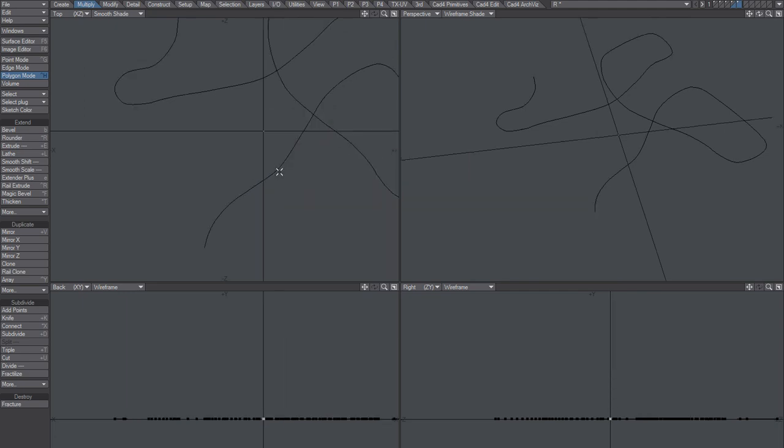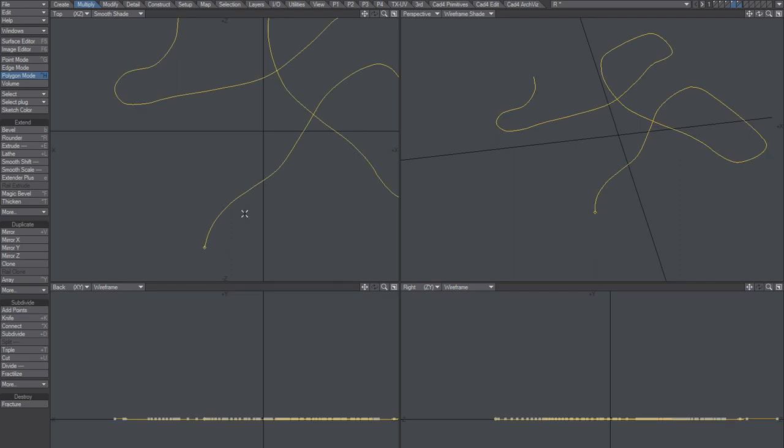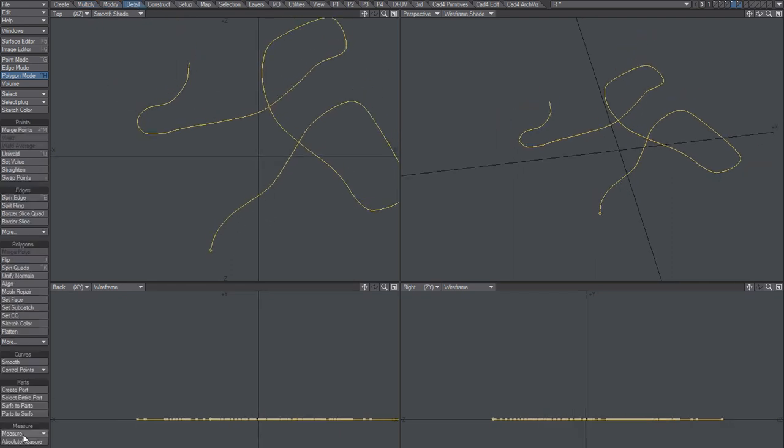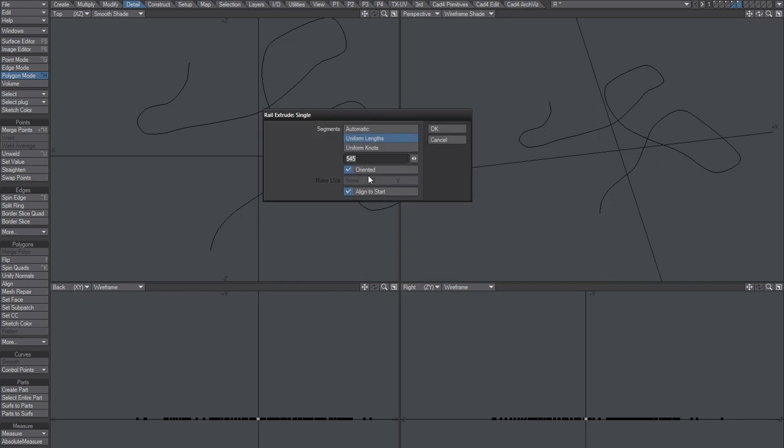The thing though is that how long is this? Well, for automotive detail, we go to absolute measure and we'll find 10.9 meters. What I'll do is I'll use rail extrude and this 10.9 and add a 0.